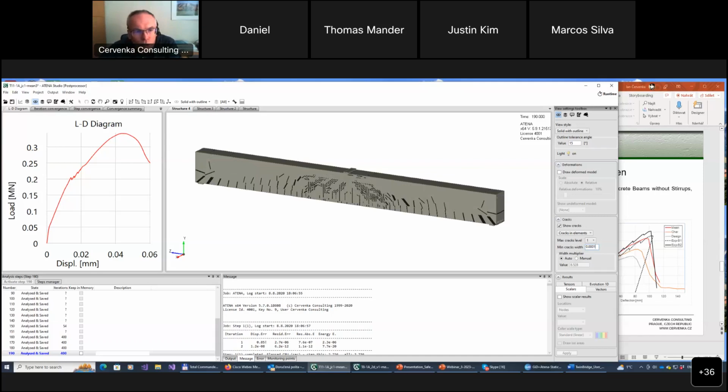Once you do that, you see the cracks start to be much more meaningful, and it will give better information about the localization. So you could play with this limit. I really recommend every time you are trying to make nice figures for publication, play with these settings. Definitely, I recommend to put a minimum crack filter. Also show only the first cracks. Those are usually the major cracks.